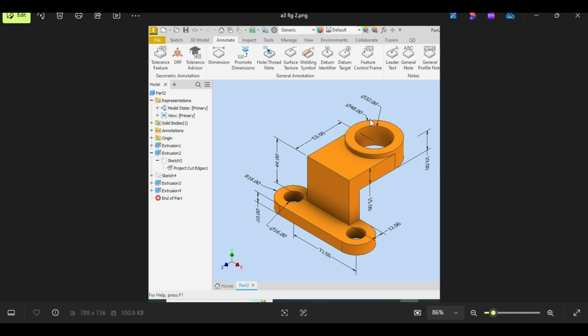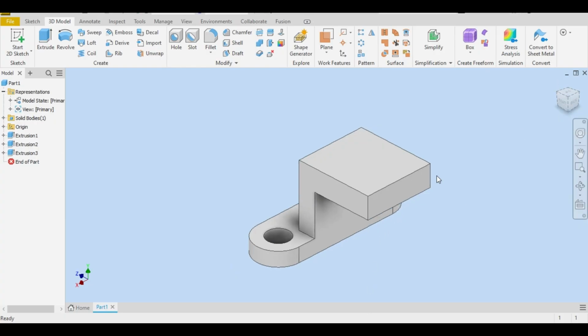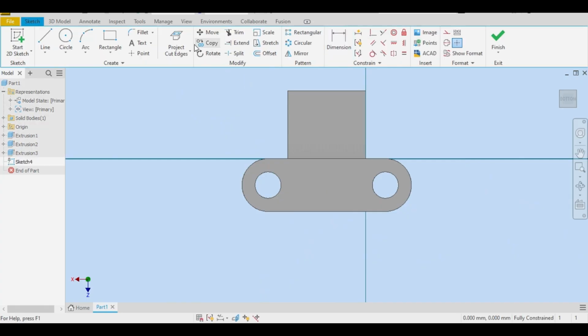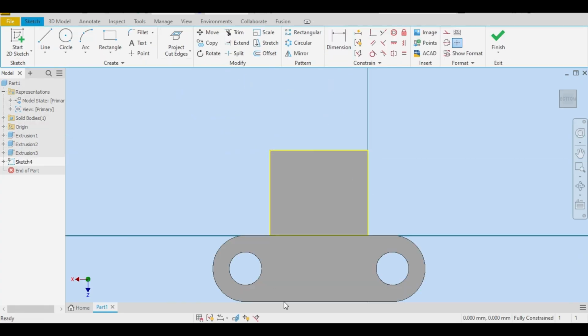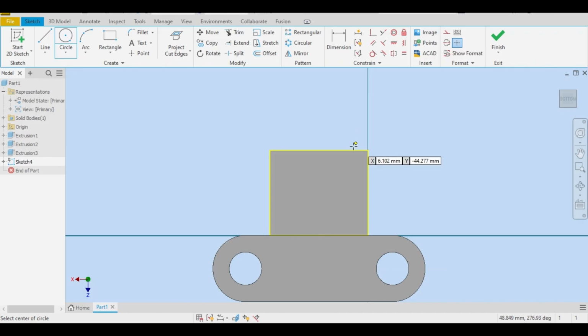now create two circles here in the middle. I will choose the middle plane here, or just simply 19 millimeter from the bottom, this face to 19 millimeter up. Let's do that, 19 millimeter up. Let me create sketch here like this. Let me project cut edges and draw two circles here. Let me go back to the sheet, the 32 millimeter and 48 diameter.